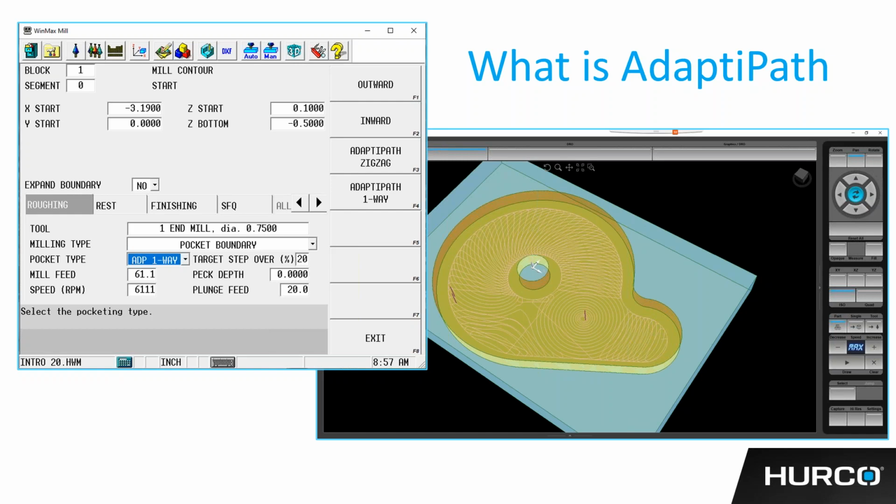Basically all of these toolpaths have a few similarities between them. You're going to be taking a large depth of cut with a smaller width of cut. Essentially, whatever your flute length is on your end mill, if you need to go that deep, that's what you're going to take. If you've been watching machining videos online, you've probably seen this type of cut. It's what a lot of people use to get a more efficient toolpath. And we'll show you how the control makes this available as an option.